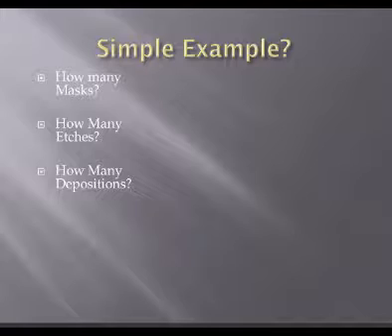You had to etch away, when we were all done, we had to take the thing up from underneath. 3. There's always one. So we etched the pattern of the hole, right? And then we etch the structural layer. So we have 2 etches, and you make a good point, right? We do have the release etch, so there's 3. There's 3 etches, 2 mask layers, 3 etches.